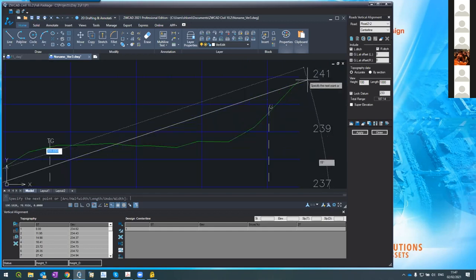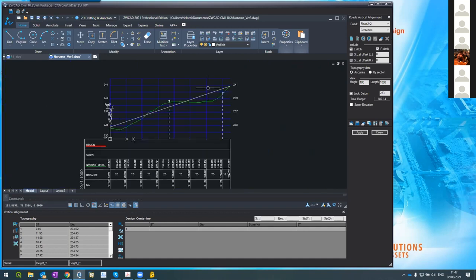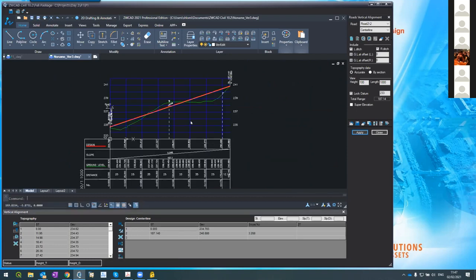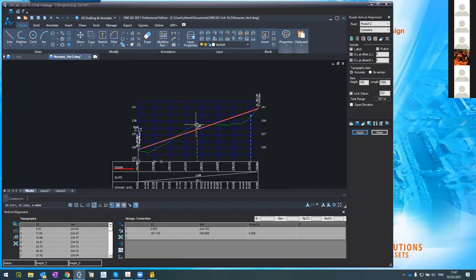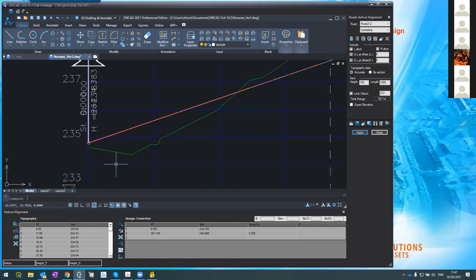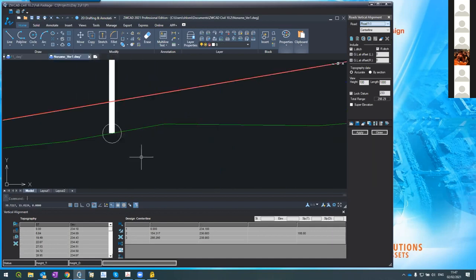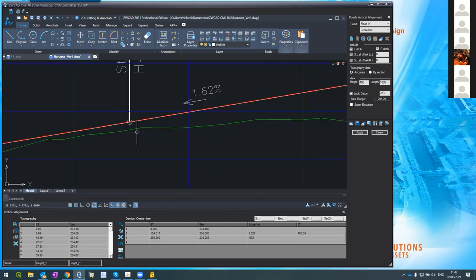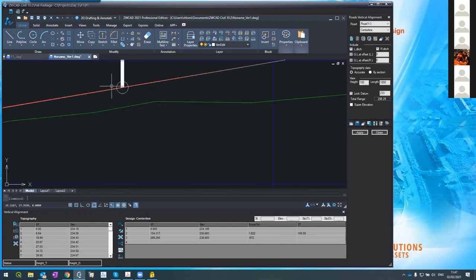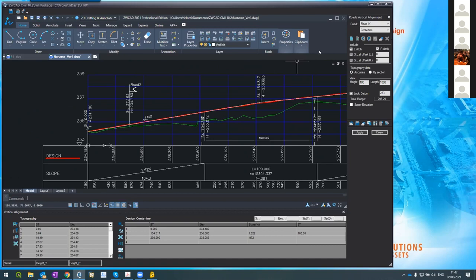Okay, you know what? I'll do it like this. Cutting and filling, like this. Which slope is it? It's only 3%. It's not a drama. Good. So I change this. By the way, if I go back to road number 1, it's supposed to take the flag up. Let's see. Here it is. It automatically refreshed and took the flag up because I changed the elevation. So the interaction is automatic. You don't need to do anything.